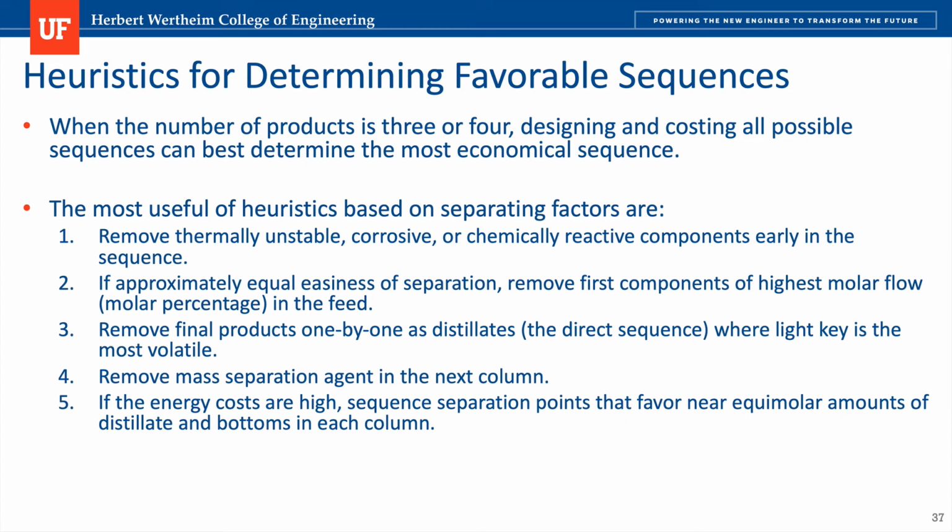And we want to do this because we don't want to overwork the condenser and the reboiler, which are going to be related to the cost. Also, the right vapor-liquid combination in the feed will avoid distributions of composition between the boilers and the bottoms and the distillate.